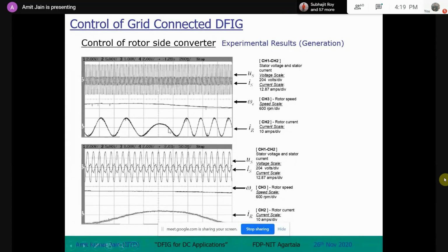Because in one case the power is coming into the rotor circuit. At 9 meter per second power is going to the rotor, but when you are working at 11, the power is going out of the rotor. So the phase sequence changes on the rotor side. On the stator it will not change, because the stator is always output only, since it's a generator.